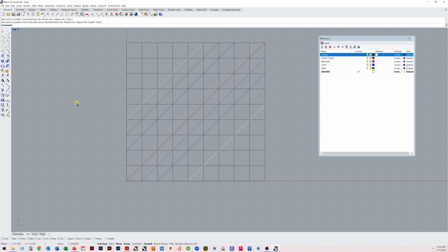And so, thinking about using your offset commands, we used 1 inch. You could now do something like 1/4 of an inch, and start to offset these lines and make different patterns with them. And as they extend outside the grid, we can come back and use that trim command again. Get rid of those extra lines.